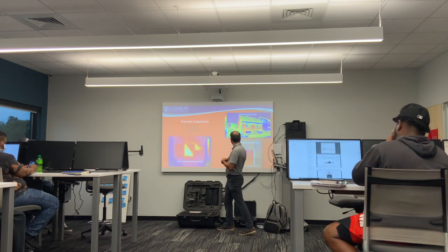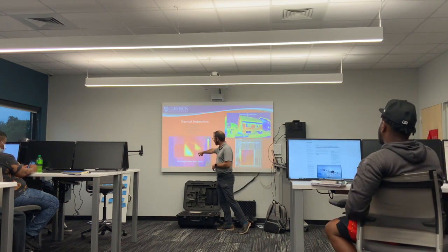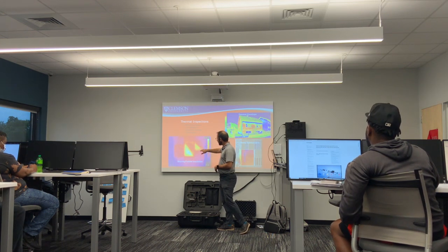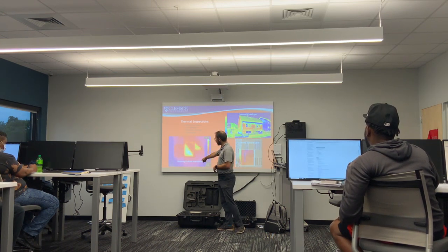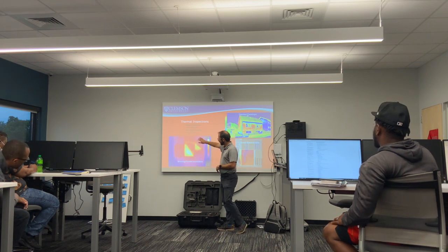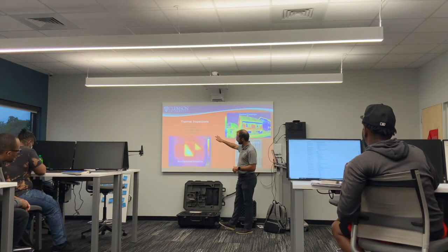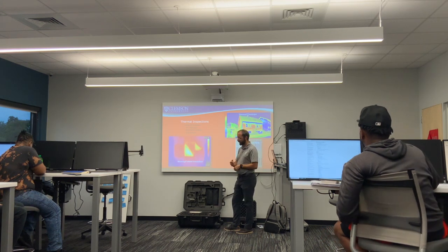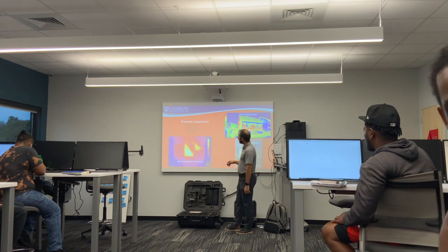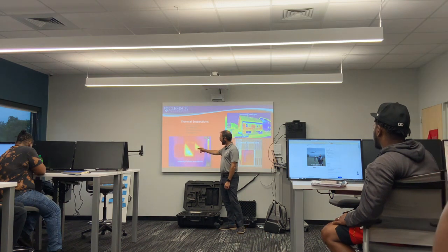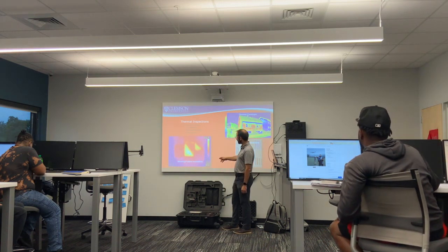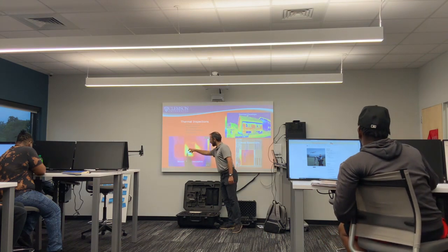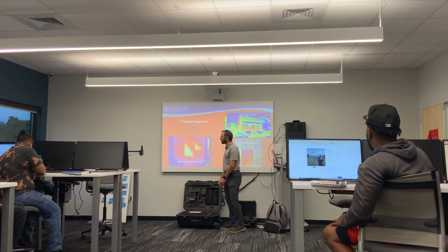Moisture leakage, so this is from a roof, so you can see missing or folded insulation. The way that a bitumen roof is created, you basically just put tiles and then paint tar over them, so you can see if something gets messed up there. You can tell the temperature difference. It looks like they missed that, where it's showing a hot spot.